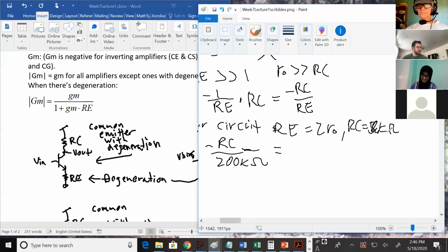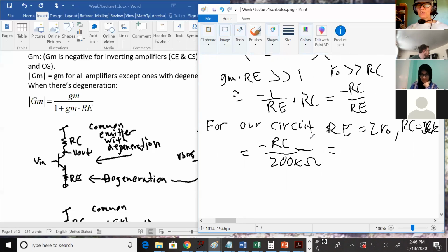All right, so if you have 2K over 200K, what's your gain? That's pretty darn good. So you want your ACM to be very low. That means that you can have noise on both of your inputs. If it's the same noise, it just disappears, doesn't show up on the output.